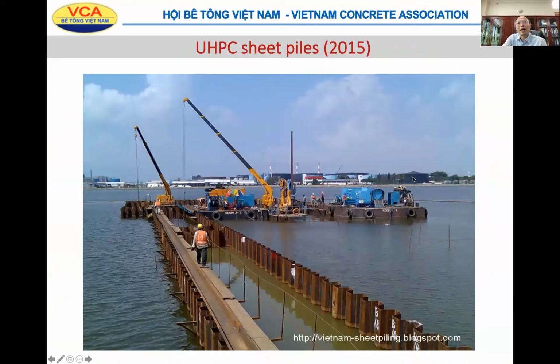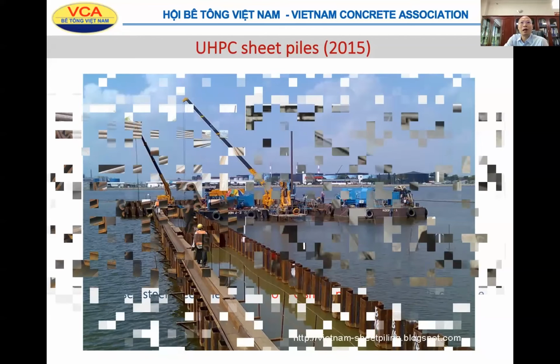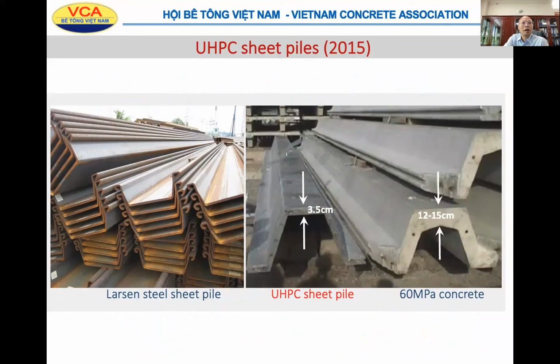One of the quite large applications, we used UHPC to replace the concrete sheet pile in 2015. And you know that in Vietnam we have quite a long sea coast. Commonly, the contractors use Larssen steel sheet piles, and also concrete sheet piles with 60 MPa compression strength. That's still quite popular in Vietnam. In this application, the group tried to use UHPC with a thickness of just 3.5 centimeters.